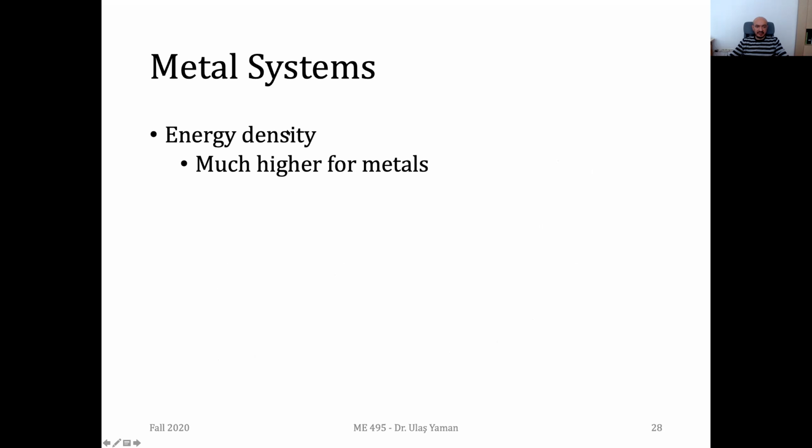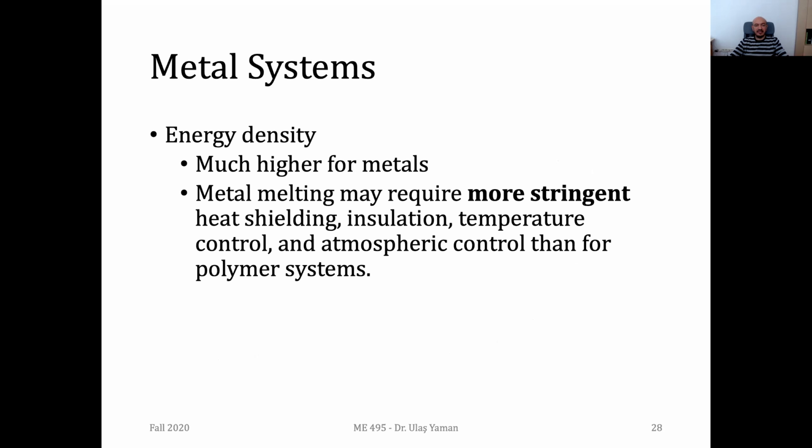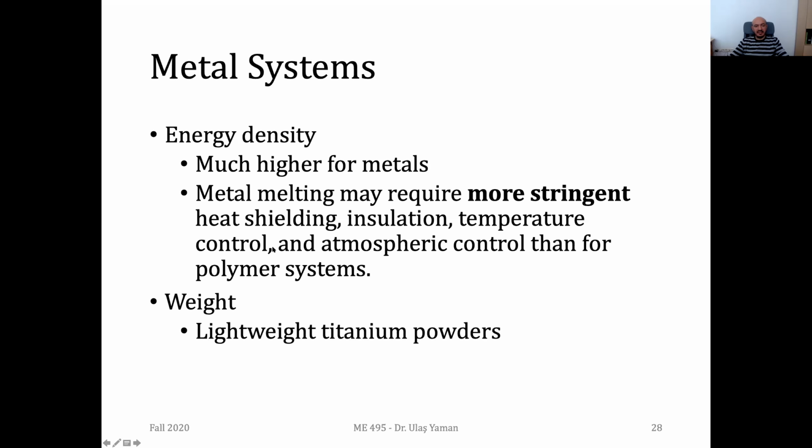And considering the energy density, if you want to use metal powders, obviously your laser system should have more power to give more energy to your powders so that your temperature will be much higher and they will be melted and join easily. So it's quite difficult to construct such a metal 3D printer. And another issue is that the weight of the parts and the weight of the machine is much higher once you are using the metal powders. Another issue is that